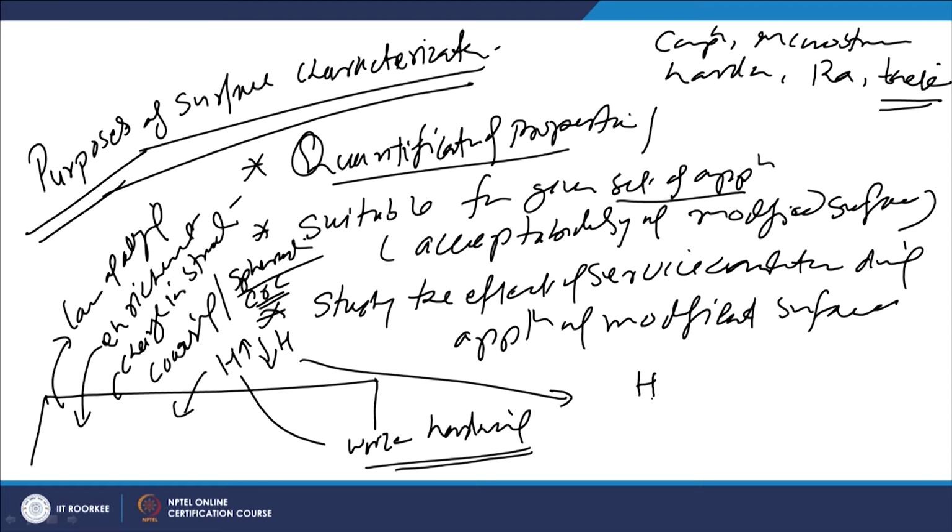Any change which is leading to a variation in properties, in terms of increase or decrease in hardness, in terms of chemical composition like loss of alloying elements or increase in concentration of certain alloying elements, or coarsening of the grain size, or the phases being destabilized. So, the metallurgical properties are getting modified due to the exposure during the service conditions.